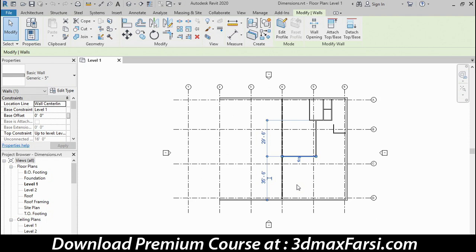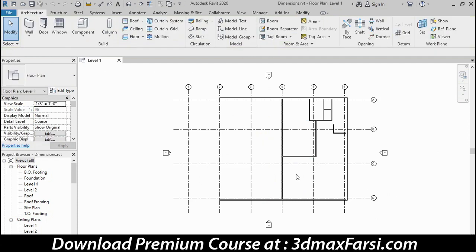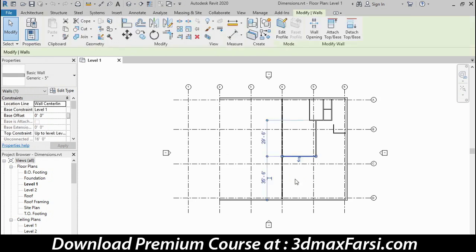Those are temporary dimensions. And they're called temporary because if you come over here and click an empty white space, that will deselect the wall and the two temporary dimensions will disappear. So they're called temporary because they only display while something is selected. Now, notice that when I select that wall, the dimensions will automatically choose where their witness line locations will be.